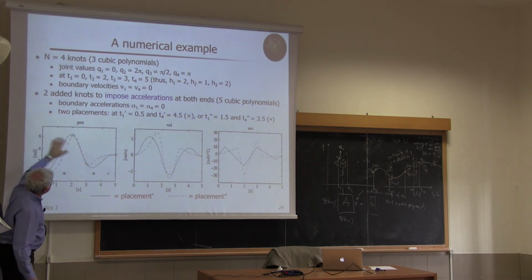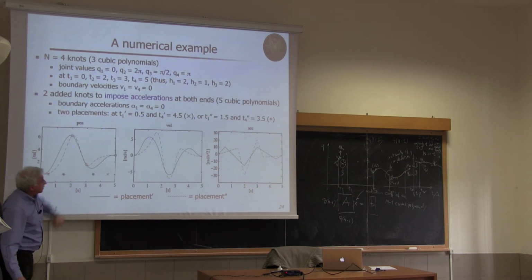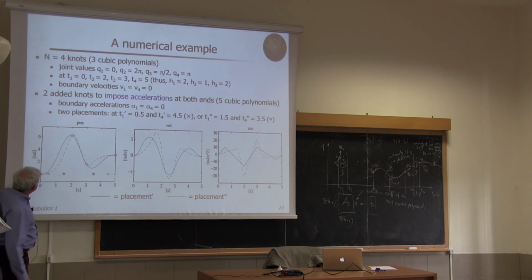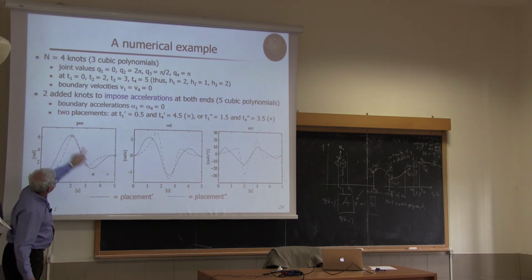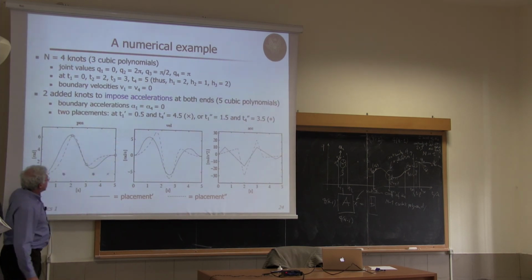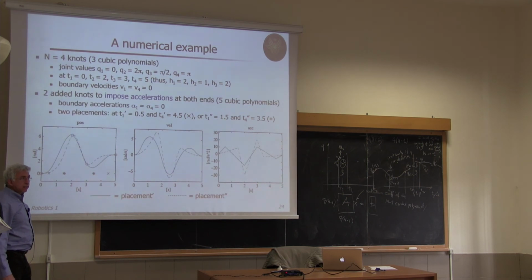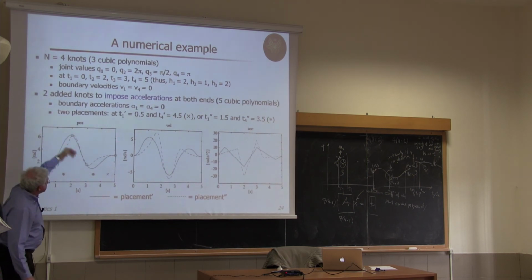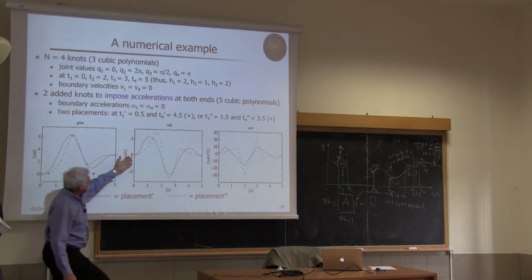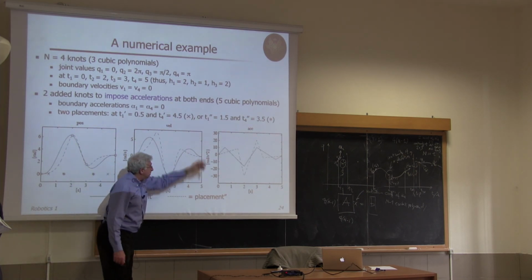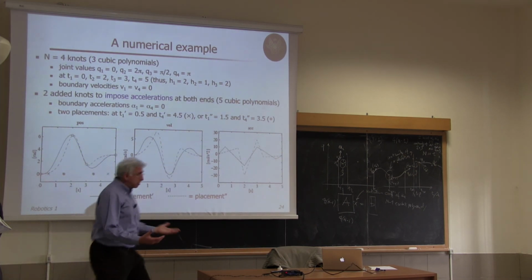And you see that when you solve the problem, you have different splines. This is the first interpolation one. They all pass through the knots. They all have same initial and final velocity and same initial and final desired acceleration. But the path is different, or the evolution is different, and same in velocity and same in acceleration. Okay, so this is the result.